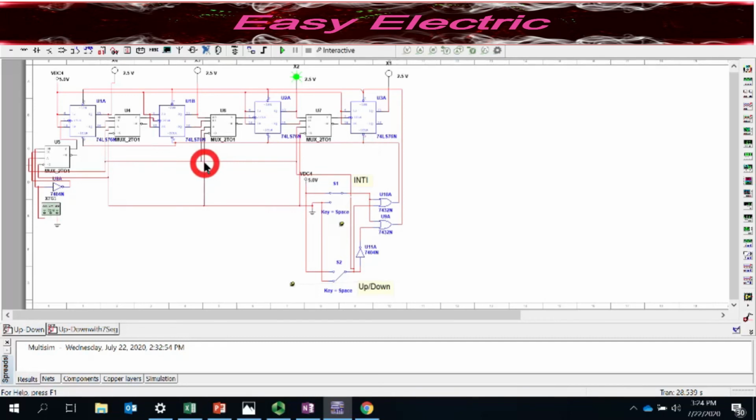As you could see, you have T flip-flops, but I just use the JK and connect J to K. If you connect J to K, you have made the T flip-flop, okay? These are the 2x1 muxes, which is U4, 6, and 7, the same thing that I already explained, okay?